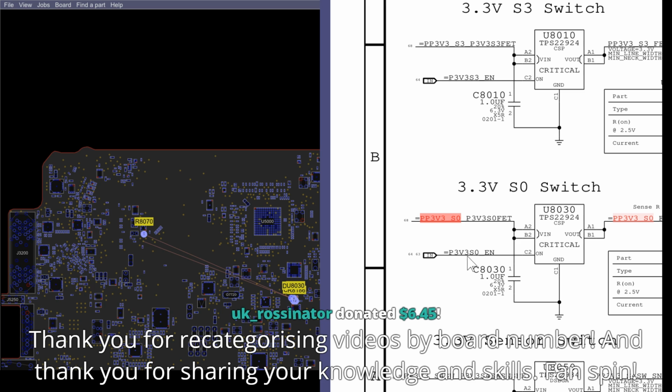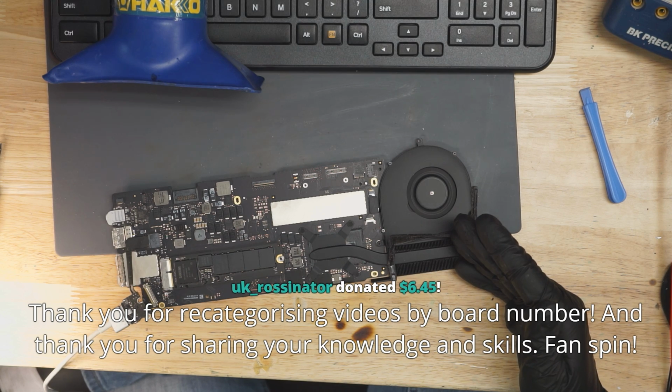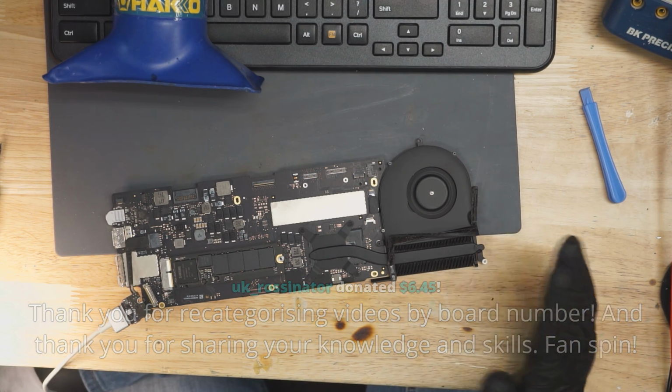We saw that this enable was present. So it says P3V3_SO enable. That's going to the on pin of the chip, which is going to be obviously the pin that turns it on. You don't got to be an electronics engineer to figure that one out. And U8030 over here was broken. Even though it didn't look broken, it was broken. And when we replaced it, we got fan spin. Since we have fan spin, we can be guaranteed that this works without any sort of further testing or quality assurance.